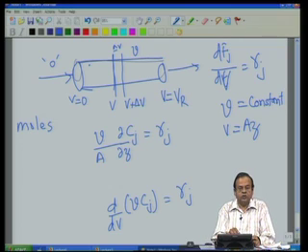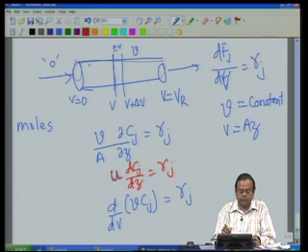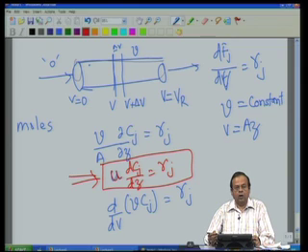What is V divided by A? The volumetric flow rate divided by the cross section area. So, that is nothing but the velocity, the superficial velocity of the fluid in the reactor, and in that case we get our mass balance equation, which simplifies to U dC/dz equal to Rj. This is the equation which you have probably seen as a design equation earlier, but this equation is applicable only under a specific case.